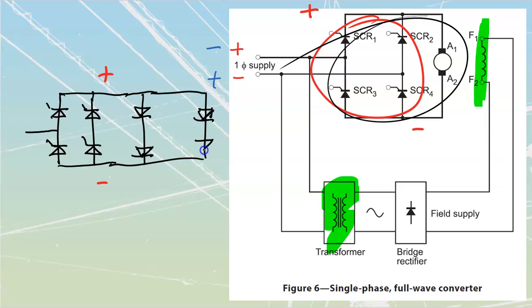Let's go like that, over there, here, here, and here, where I'm going to have sets of SCRs, with my armature connected across the center, like that. Obviously, this is just going to be terminals, leads that are brought out on the board for that. But the ones highlighted in yellow only need to create my value of DC, positive, negative. They don't actually need to be SCRs. You can use just straight diodes to get DC out of there.